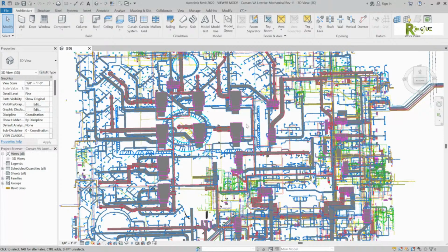But I would like you to try, and if Ginger's still listening, or if she comes back to listen to this, I'd like you both to try to draw a building using those commands that we went through. Have at least 4 walls, at least a couple doors, at least a couple windows. Don't just put the standard ones. Show me that you know how to load a family. Put some furniture in there. See if you can make the kitchen and the bathroom and the bedroom. See if you can use the commands that we went over. And then Sunday, we're going to learn how to annotate those and turn those into drawings.